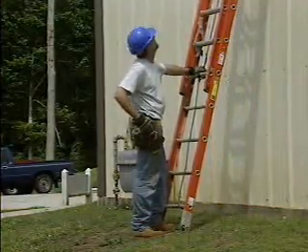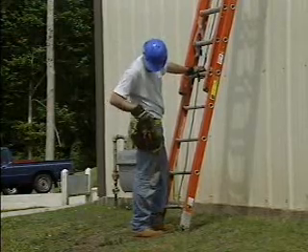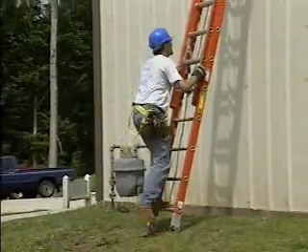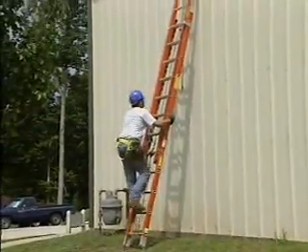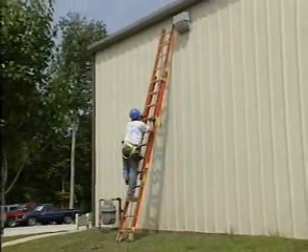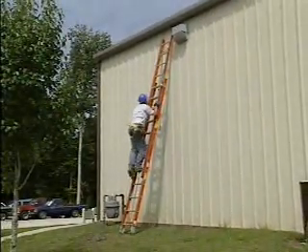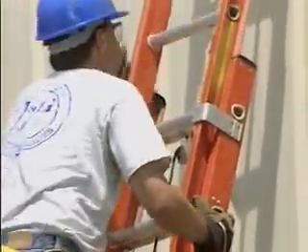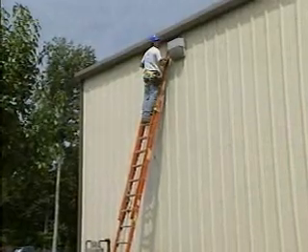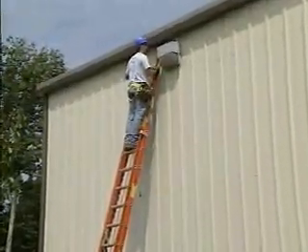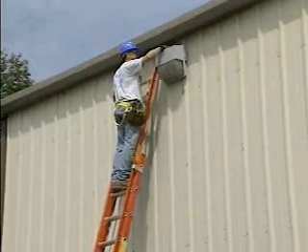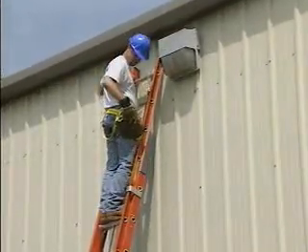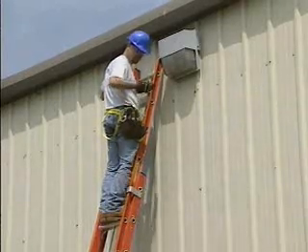With the ladder in place, the worker makes sure that he has all the necessary tools for the job. He carries the tools in a tool belt to keep his hands free for climbing. Then he slowly climbs the ladder, using both hands to hold on to the side rails or rungs. He keeps his body close to the ladder so that he doesn't tip over backwards. In this case, the worker will perform the work from the ladder. If he needed to step off of the ladder onto the roof, he'd have to make sure that the ladder's side rails extended beyond the top of the roof by at least 36 inches.